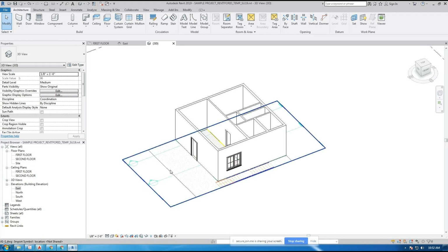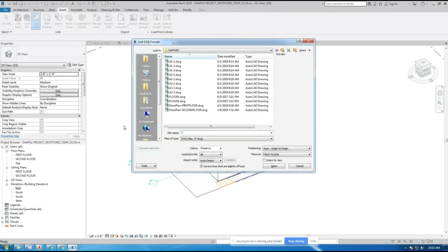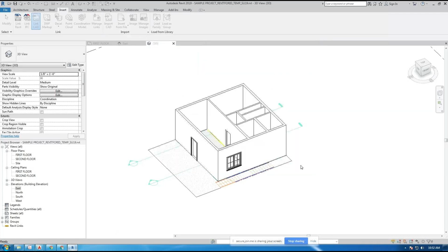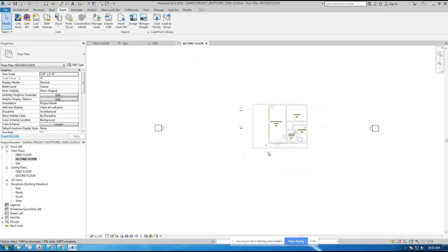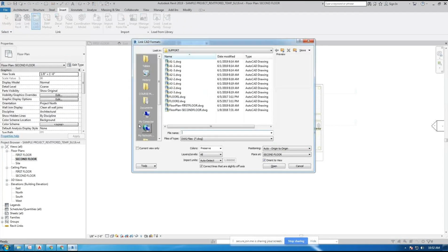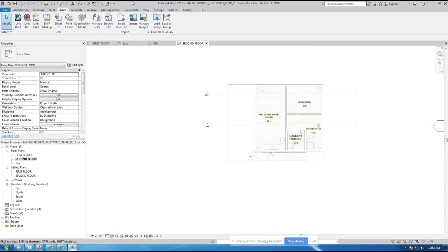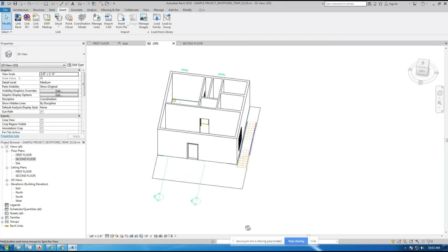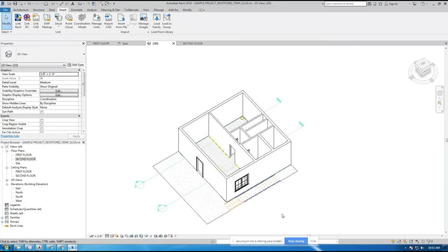it or not. So when you insert a CAD drawing into Revit here, and you pick a drawing to insert into Revit, let's say, for example, my second floor plan. Here's a link. You see this button here says current view only. The Revit file will only show up in that view here if you check that box. You will not see it anywhere else, including the 3D views. So sometimes you might not want to see it in elevations, sections, but you might want to see the CAD drawing in 3D. Well, you lost that option if you check that box.